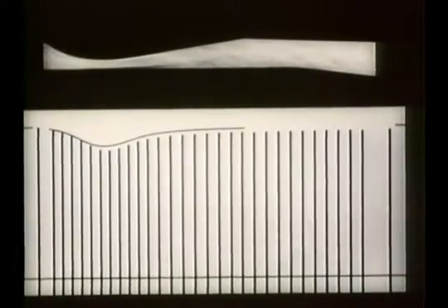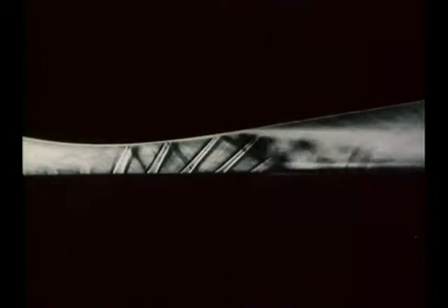Now let's go on to look at some properties of supersonic flow in our channel. We have roughened the flat wall of the channel with strips of plastic tape. The object of the roughness is to produce small disturbances in the flow as an aid in visualization. There is no visible effect on the flow until the shock wave appears. Then characteristic disturbances called Mach waves appear in the region between the throat and the shock wave. These Mach waves, which originate at the edges of the tape, are evidence of supersonic flow in the diverging part of the channel.